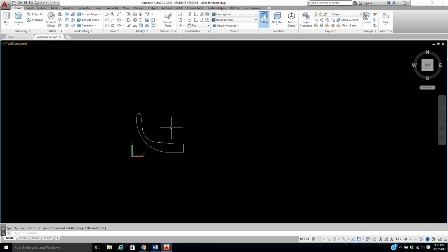Now, that's our shape. That's our profile. Think about it if we spun this around in a circle. And mind you, it's going to become solid. It's not necessary. We could use this as our revolving line, but I'd rather draw you a line so you can actually see what I'm talking about. So I'm going to take a line, and I'm going to randomly draw it. I'm going to put my ortho on so it's perfectly straight. And I'm going to go ahead and move this line.